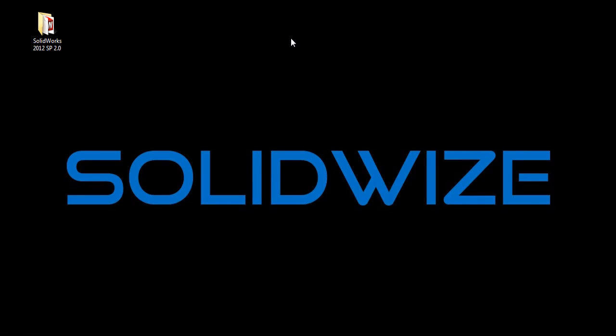Windows Vista, I've never had any luck with SolidWorks, and I would completely avoid it if possible. And if you're running Windows XP, you should be fine for the most part. Once you have all that figured out, you want to shut off any extra programs that you have running, anything that might conflict with the install. Specifically, you want to turn off virus software, as this can conflict with the installation process of SolidWorks.